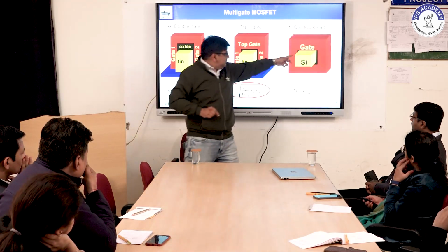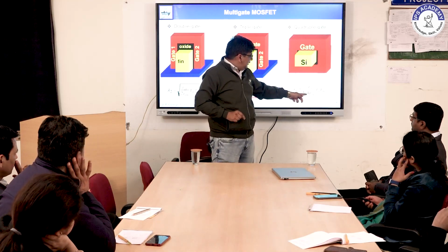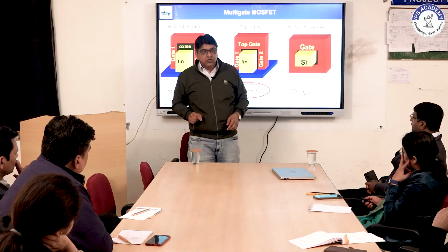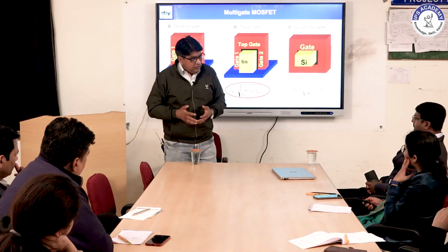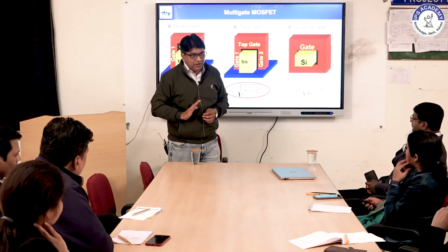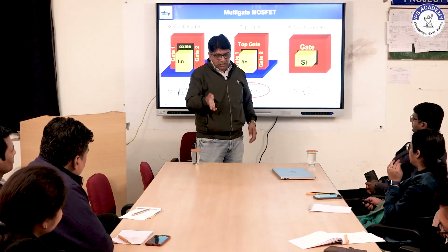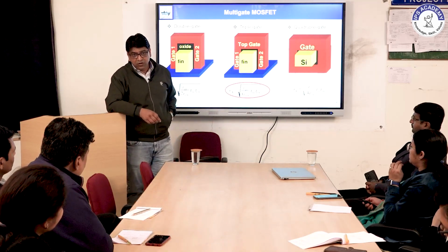You are observing in the last slide the gate-all-around structure. In this gate-all-around structure, you are observing the divide by 4. It means the electrostatic integrity factor is also improved. If its value is minimum, it means the device is more suitable and it will improve the short channel effect. It is not a leaky device. So nowadays we are using such devices. 3 nanometer, I think IBM has introduced, and they are working on this one. They have come up with some production also.